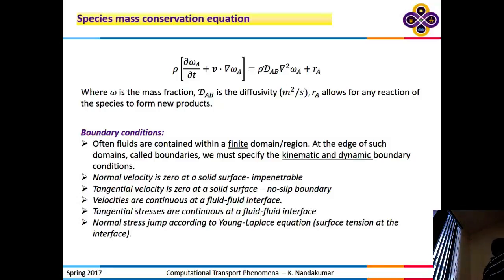And similarly, you have to say that the stresses are continuous across that interface, the tangential stresses. But you don't know what they are. So impose the condition that the tangential stresses are similar. COMSOL automatically does all these things for you. If you identify the interface as a fluid interface, these conditions are automatically invoked.